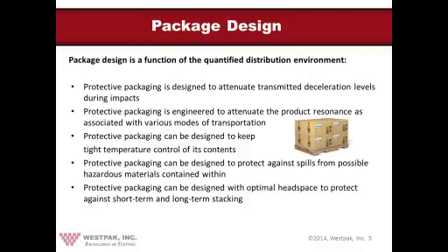One of the functions of a protective package is to mitigate shock into the product, which can occur during drops, kicks, and objects impacting it. Shock can also occur during the sorting line and distribution hubs, where diverters programmed to shift packages weighing over 70 pounds make contact with your 5-pound package. You can imagine the force of the impact. The cushion system should be optimally designed to attenuate the deceleration levels to a level less than the fragility of the product. Another aspect of a protective package is to attenuate vibration resulting from transportation.